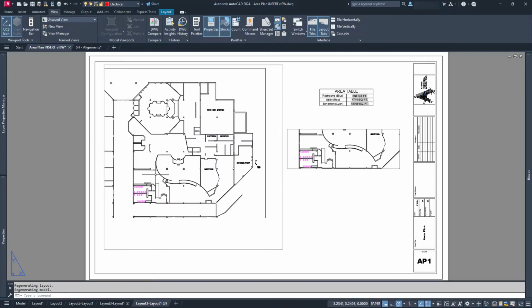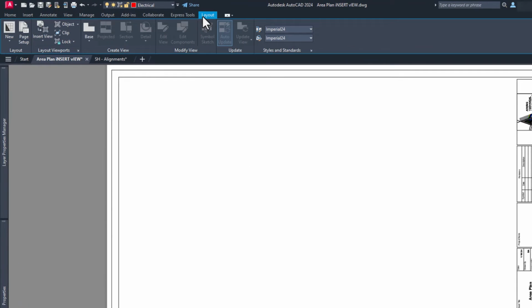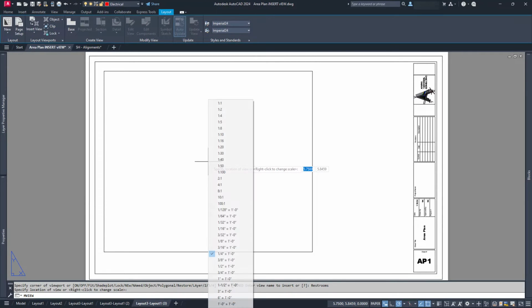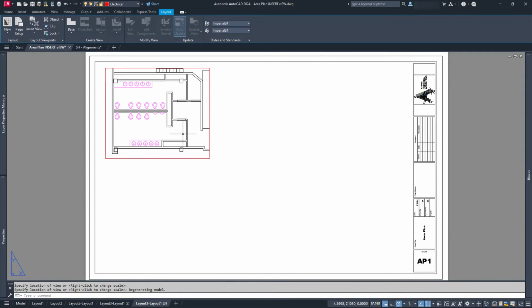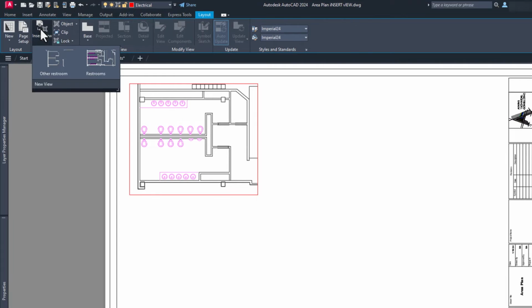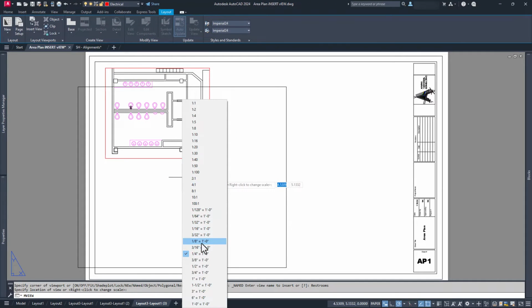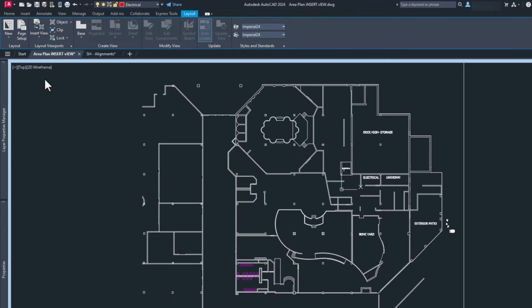So how does this tie back into Insert View? Easy. Once you've named areas of model space, these named areas will show up as options in the Insert View command. Choose one of the named views, right-click to set the scale, and left-click to place the viewport. If you are working on multiple viewports of the same area, this makes creating consistent viewports almost idiot-proof. If you want to use the Insert View tool to place an unnamed viewport like we did earlier, you simply pick New View from the command, and it works like it did before.